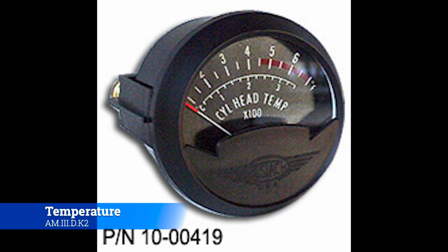And when we started looking at it, one of the ignition wires had failed on us, and that was the problem. Now, had we had a cylinder head temperature gauge on the dash of the plane and had been watching it, we would have bypassed a lot and just said, hey, look, the number 1 cylinder right here has failed on us, and we're not really sure why. And come to find out, it was just a wire. It was a really simple fix, and then the plane was back in the air. But CHT would have been very, very helpful in that particular instance.